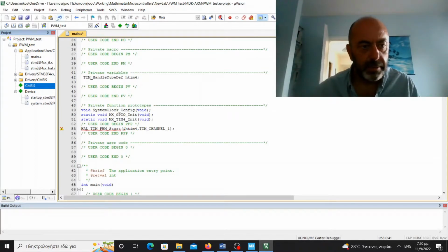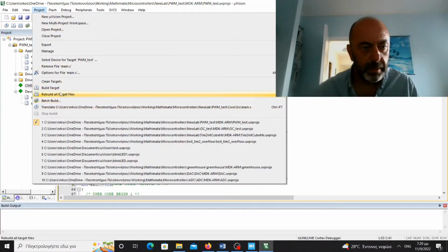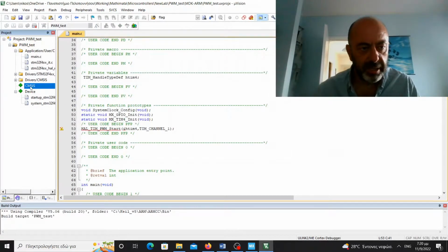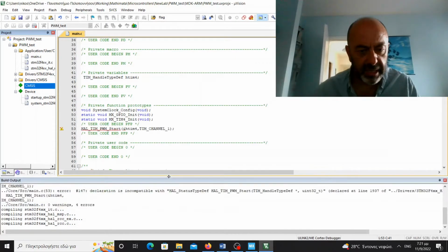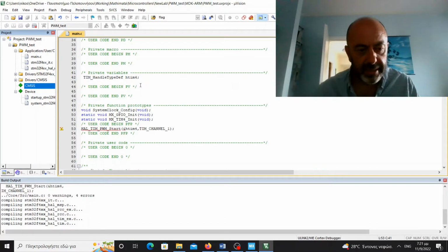So let's build the project, build target. Maybe I have to change something later, because maybe another file will appear under this folder CMSIS with the same name as this one, as happened in my previous video, but maybe this does not happen if I tick the startup option immediately before building the project the first time.